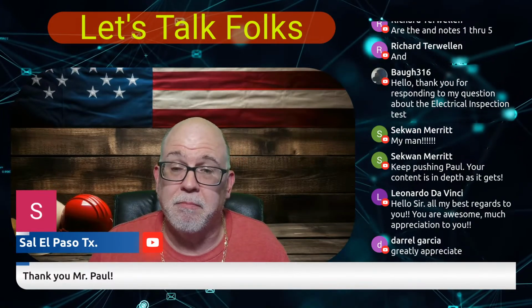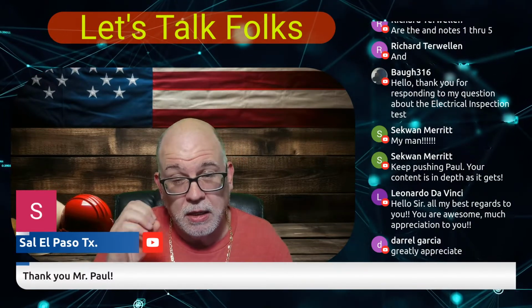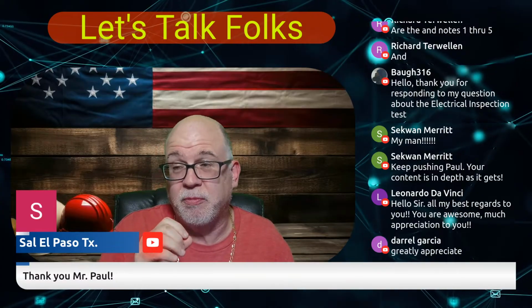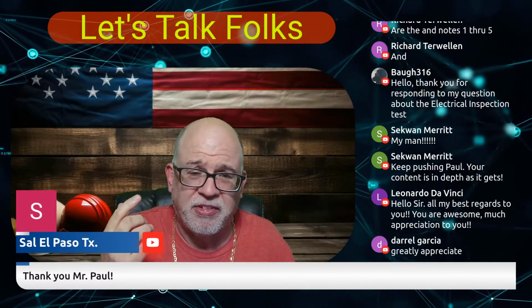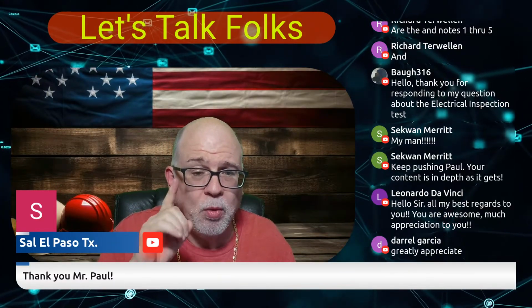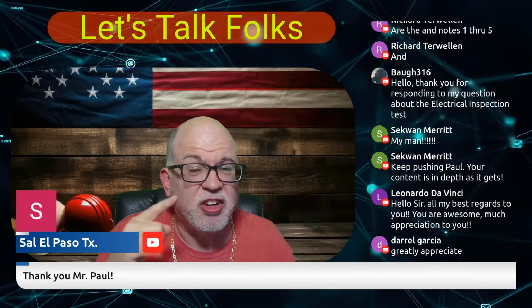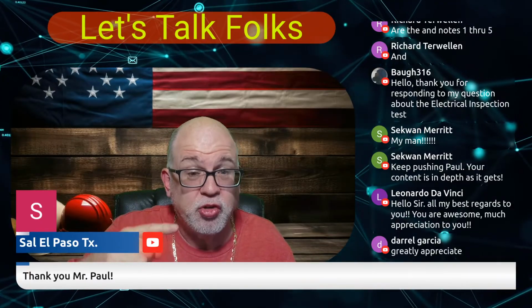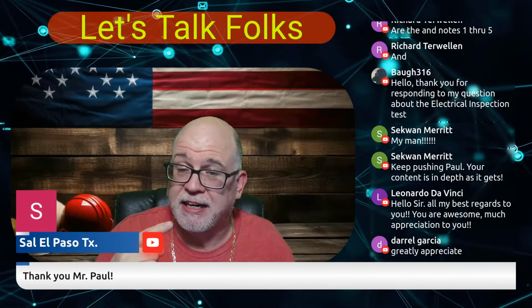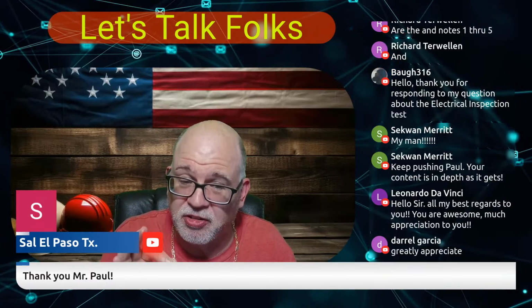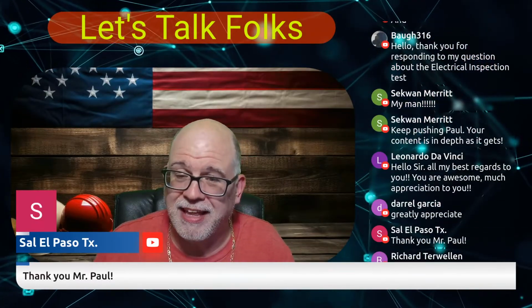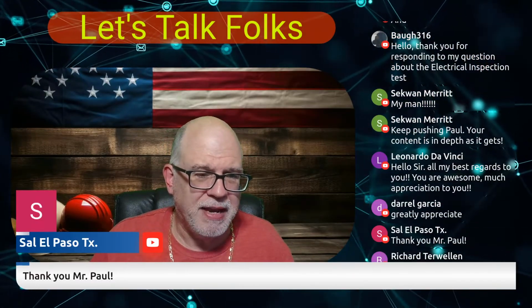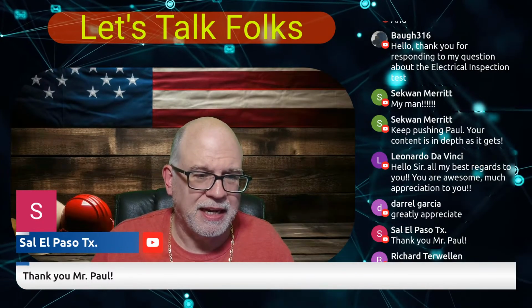That'll be talking about motor branch circuits, and not the normal, whereas people know that you just do 125% of the FLC. But we want to make sure that you understand that if there is an adjustment or correction due to ambient temperature or more than 3 current-carrying conductors, you've got to take that into consideration as well. So we're going to cover that today. So make sure you check that out, okay?